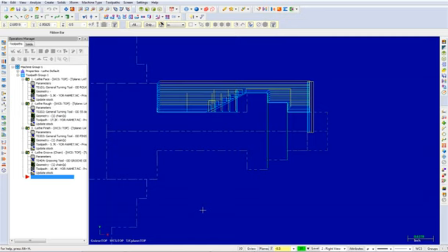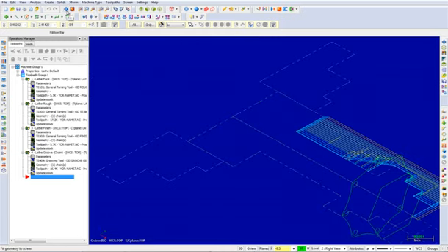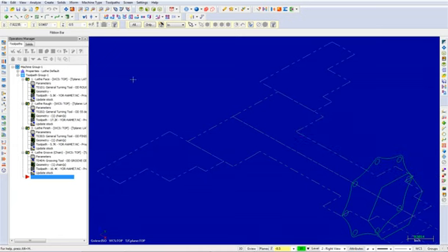From here, select the isometric view from the toolbars to see your part. Also, select Fit Screen. To remove the toolpaths from your screen, press Alt-T. Your part should appear as shown up to this point. You can use your mouse to zoom in and out on the part.